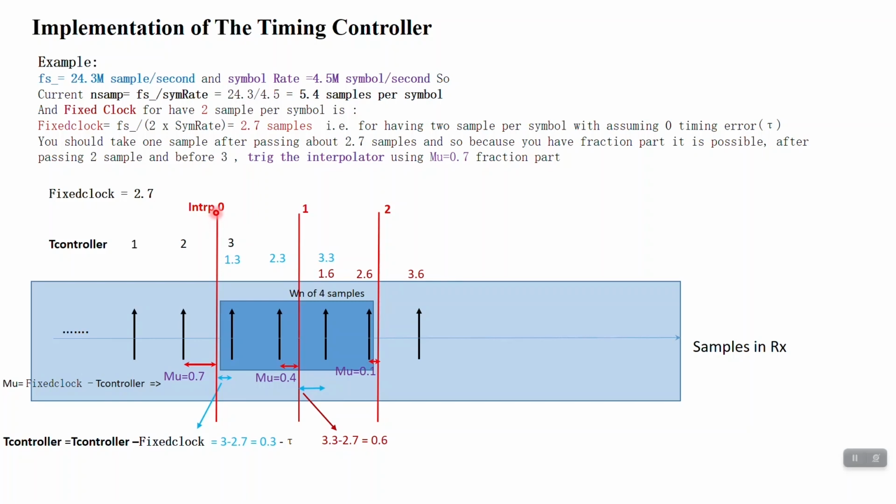You should calculate the timing error here, but because the interpolated sample before this sample didn't exist, and the middle sample is 0, the timing error here, if calculated, is equal to 0. So the timing error calculation clock is after every 2 interpolated samples. Because each symbol has 2 samples per symbol, the clock of the timing error detector is in fact a symbol clock.